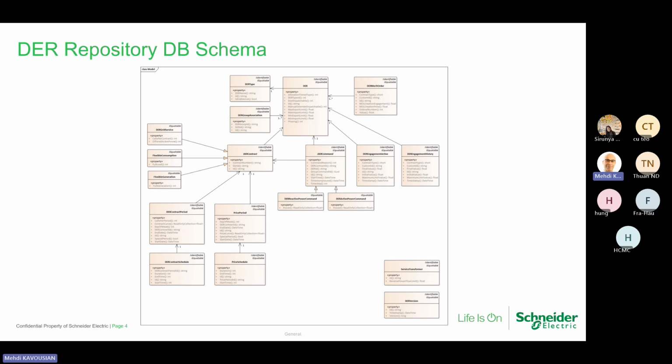When you send the command, it goes to this engagement list. It's a list of things. And next time you run active network management, because it runs periodically, it first looks at which assets I have engaged before, and I disengage them, because now maybe the constraint has gone away, right? Maybe the load is now lower, so I can disengage them. So first it disengages the previously engaged elements.